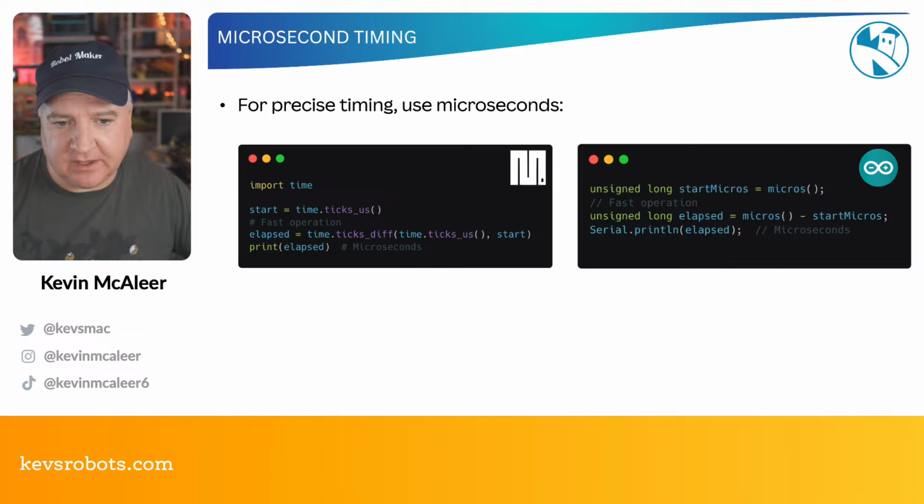On the right hand side, we've got the unsigned long startMicros equals micros, and that's how many microseconds have elapsed since the board booted. And elapsedTime equals micros minus startMicros, so we get that elapsed time. Again, you might fall foul of the rolling over comparison.